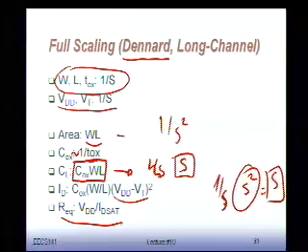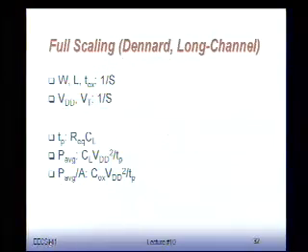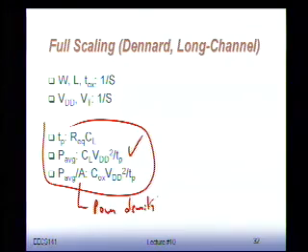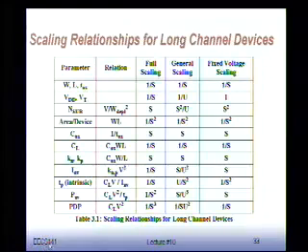which I computed here. I can also find my equations for P average, the overall power dissipation of a single gate, or the power density. This is power density. Okay? And I can find all of those things as a function of S. And then it's quite trivial for me to build these nice complex tables that we discussed. This is what your technology roadmap basically looks like.